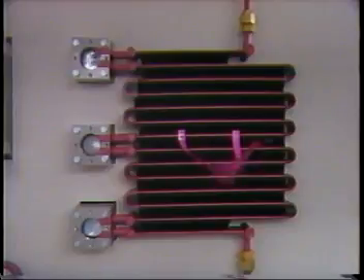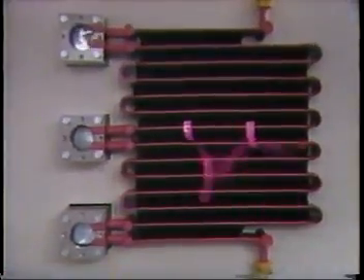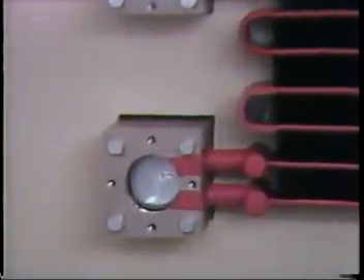But simply compressing the refrigerant is not enough to turn it into a liquid. The refrigerant gas becomes a liquid when it is cooled by the condenser. And the heat taken from the air by the evaporator is discharged outside the vehicle by the condenser.